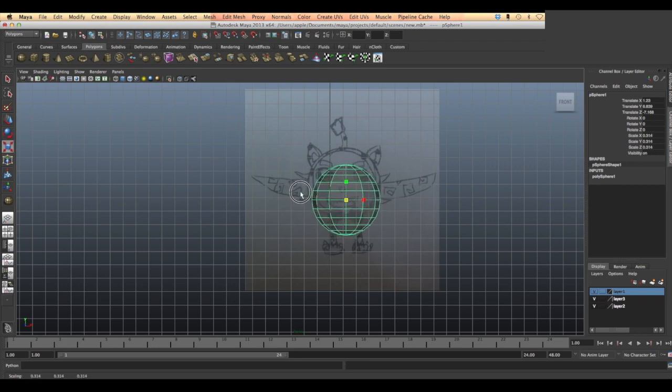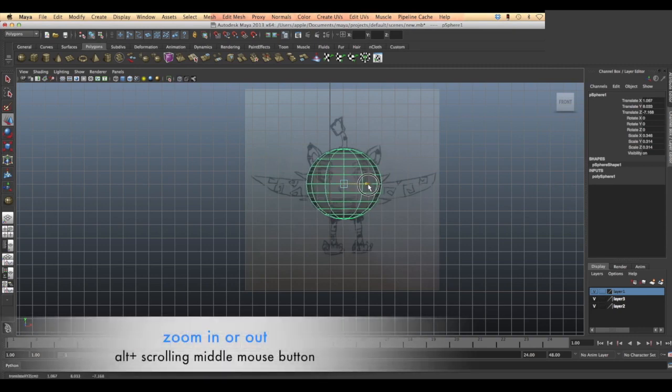So basically you can choose any box you want, like the green box will scale your object on the y-axis and the red box on the x-axis and the blue one on the z-axis. The same goes for the movement. If you want to move your object on the x-axis, you click on the red arrow and drag it.